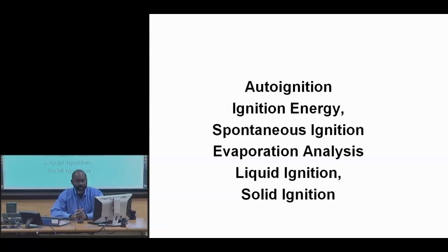To motivate some of this, I want to talk about an issue that you've heard of and oftentimes becomes, in some sense, the diagnosis or the cause of last resort when people are doing forensic reconstruction for fires, and that's the idea of spontaneous ignition. Spontaneous ignition is probably not what you think about when we describe it mathematically, but it really is just a trade-off between exothermic heat release and the insulating property of the fuel bed.